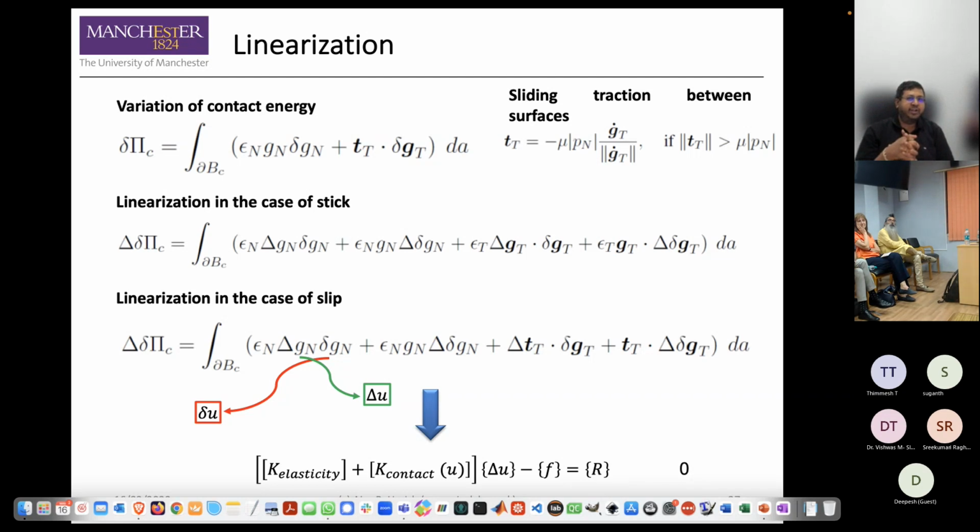So I don't think our results are representative of the real condition. Essentially, what we were looking at is, if we are able to measure the particle sizes coming out of the gross wheel test, and sample them out by size and say, okay, we have this distribution, what is the particle size that separates out when you have a crack growing in your microstructure and separates out as a piece? That was the limit of the finite element simulation that we were doing at that point, because once the particle separates out, you need to treat it as a third body in a way.